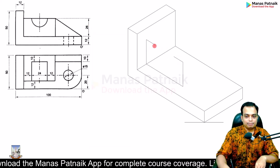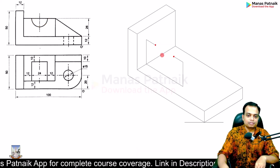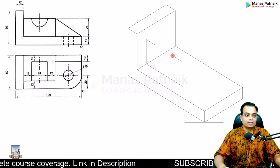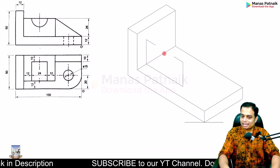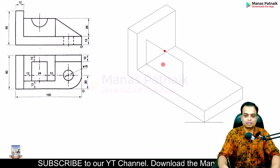Now, in between these 2 points, you have to create a sort of semicircular profile, but in isometric view. It should look like an isometric view. How do you do that? First of all, take a look now. You can connect these 2 points. You know very well that the gap between them is 24. And you can take the center also. This is the center.